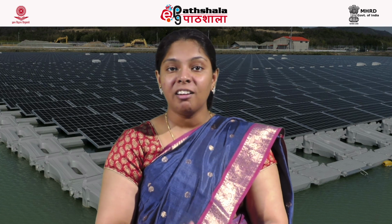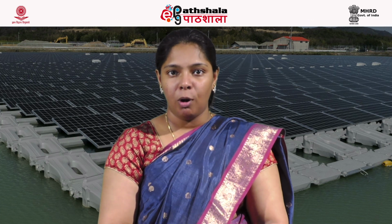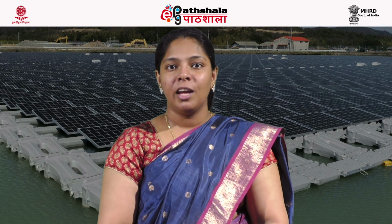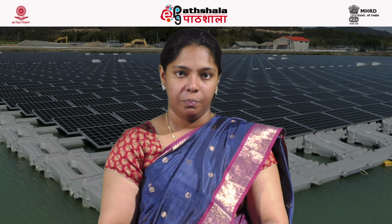We have seen some of the characteristics of the salt to be used in salt gradient ponds. And we have seen the different zonations or stratification of these ponds, like the upper convective zone, the non-convective zone, and the third one, the storage zone or the lower convective zone.